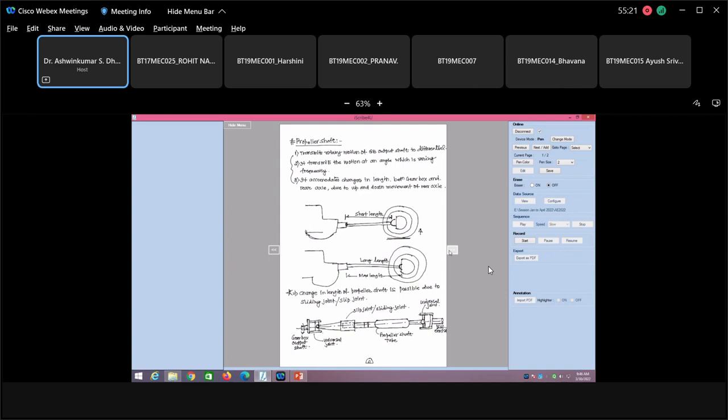You got to have the universal joints. A universal joint you studied in the theory of machines or machine design. Two universal joints, they are connected. One is at the differential end and one is at the gearbox end. As Saurabh said that in truck it is visible, so sir, he is right. So when you get the time or whenever you find that the truck is parked, just watch it carefully. You will be able to see the propeller shaft. Okay, so the total length of the propeller shaft is this particular length from here to here. The end to end, this is the length of the propeller shaft L.